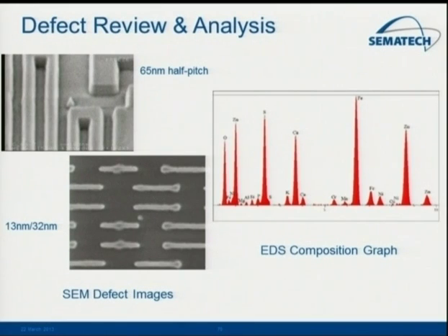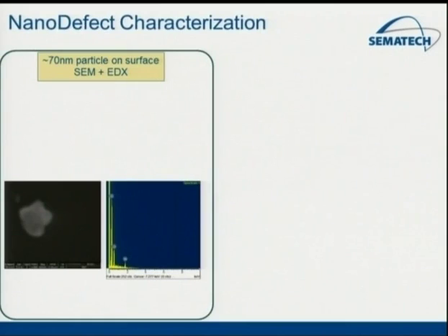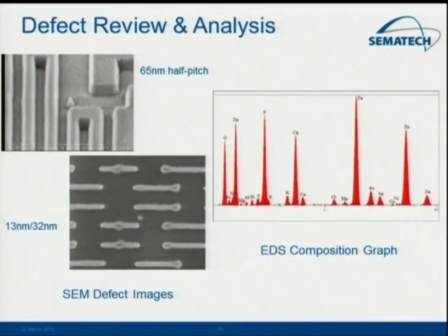And this is kind of a strange map. I can't figure out exactly what that defect is, but there's a lot of iron in it. Good chance it's probably a metallic defect coming from somewhere in your process chamber, like a mechanical interaction between the different components. So that's useful, although even this is limited by how small it can look at.